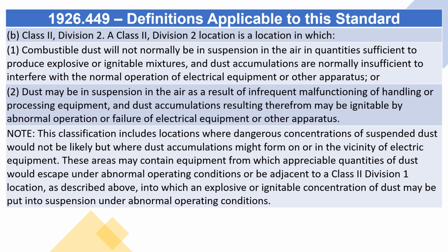These areas may contain equipment from which appreciable quantities of dust would escape under abnormal operating conditions or be adjacent to a Class 2 Division 1 location, as described above, into which an explosive or ignitable concentration of dust may be put into suspension under abnormal operating conditions.